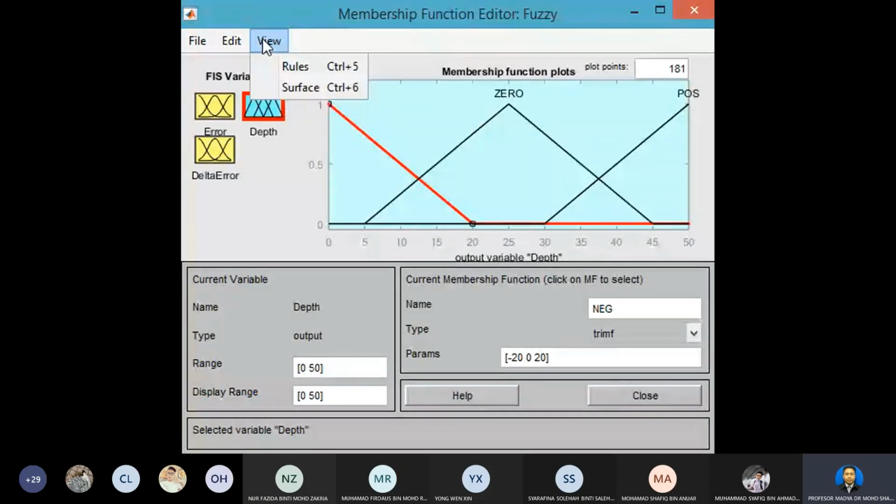That means no need to tune the rules, but you have to tune this part, the membership function editor. On this part, you have to try and error on the range. For example, the depth I set from 0 to 50, maybe I change it from 0 to 100. It's up to you. For a beginner, it will take time to get the best response for fuzzy. Right, so that's all for how to design the fuzzy logic using Matlab.